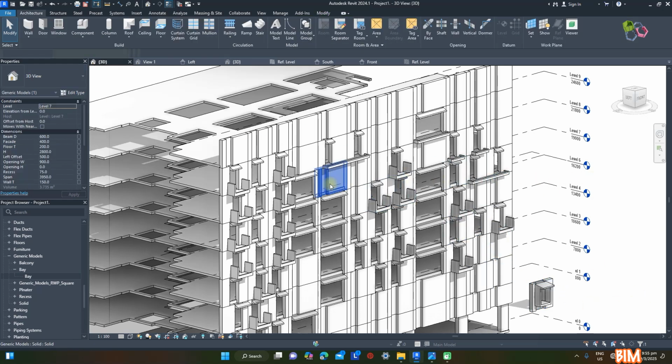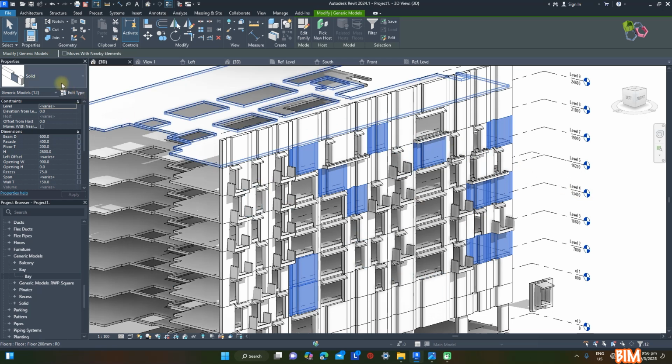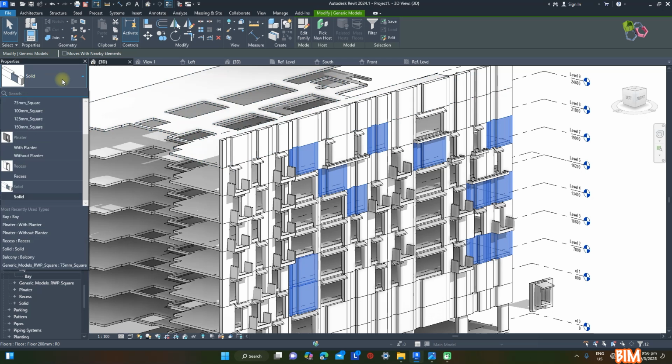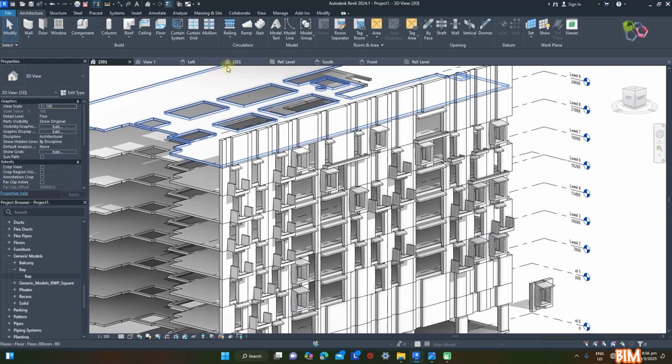This bay panel family is to swap with some already installed panels in the project. Select these 3 living room solid panels, also 2 more panels below. These 2 at below right, bedroom panels, together with the level 2 panels above. And also these individual bedroom panels, 1, 2, and this 3. Go to Properties palette, search and swap with bay family. Yes. Installed as bay panels in place.